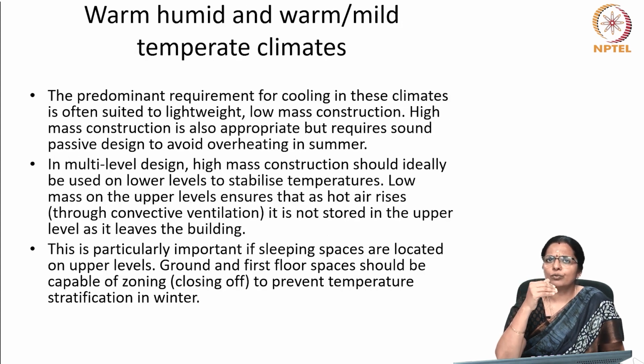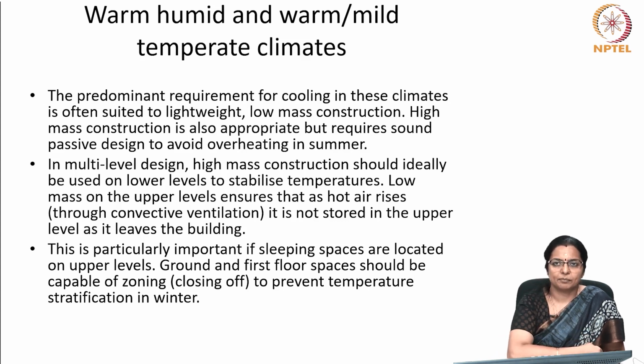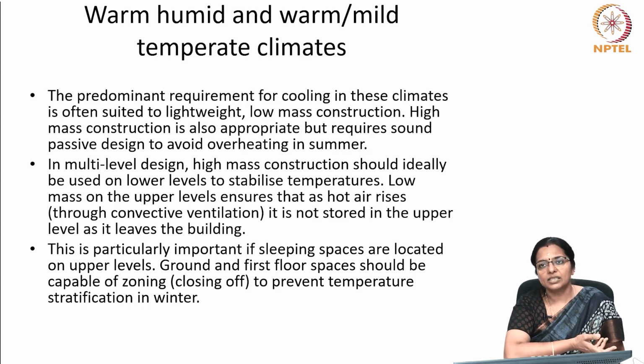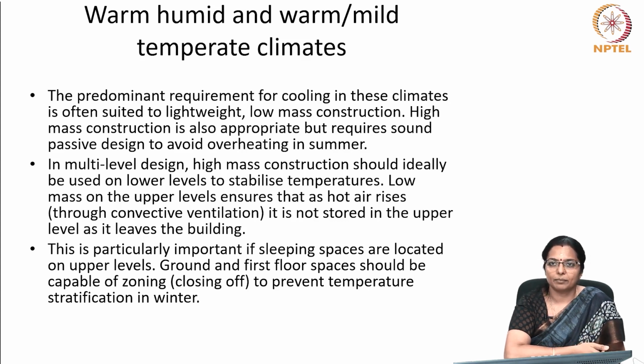What should you do in warm, humid or warm and mild temperate climates? The predominant requirement for cooling in these climates is often suited to lightweight, low mass construction. High mass construction is also appropriate but requires very sound passive design to avoid overheating in summer.